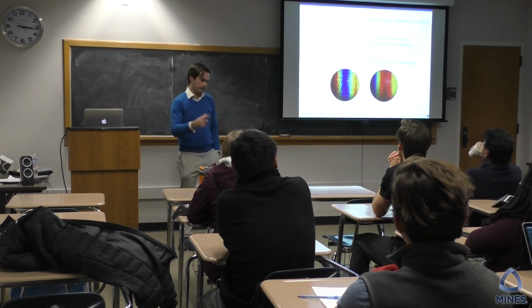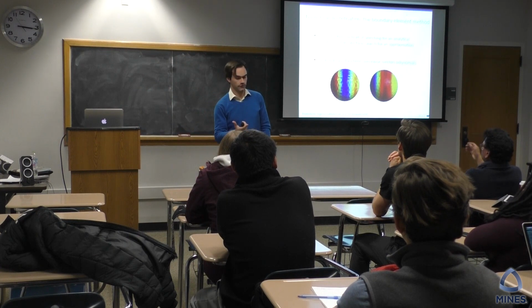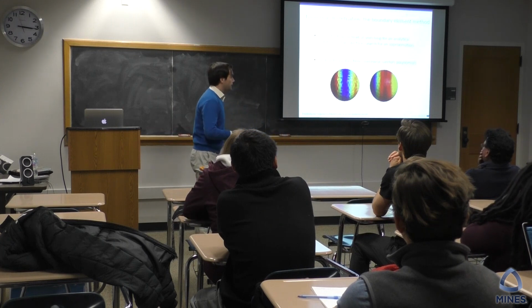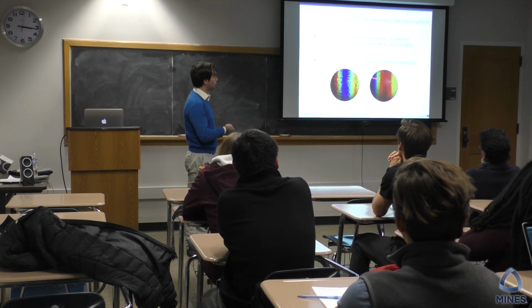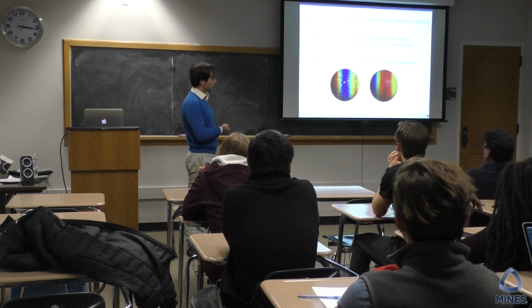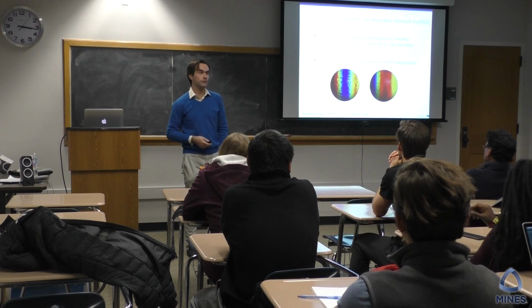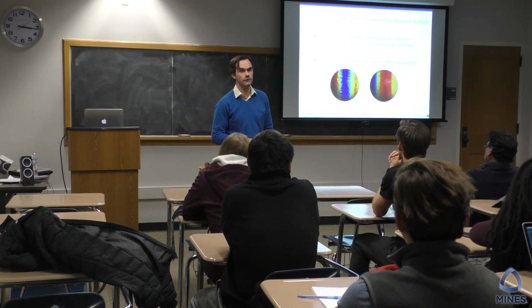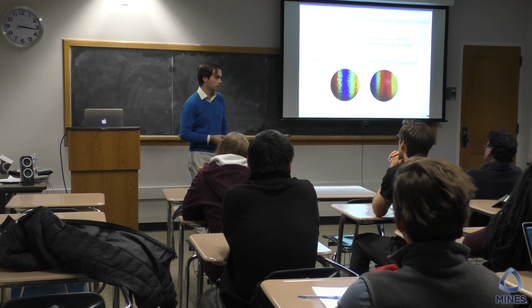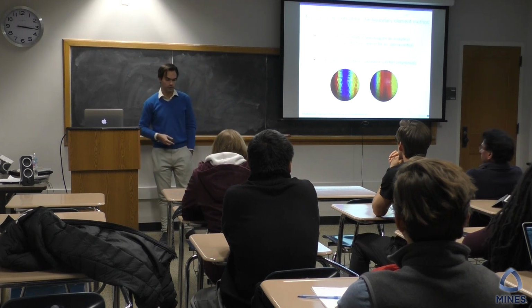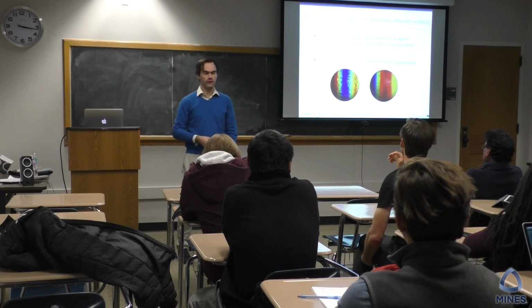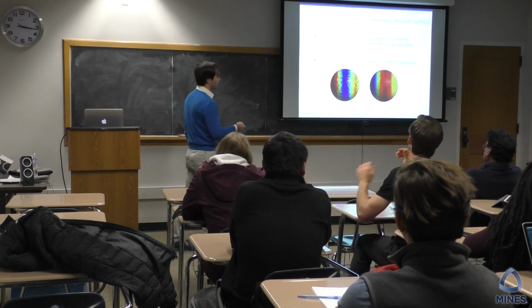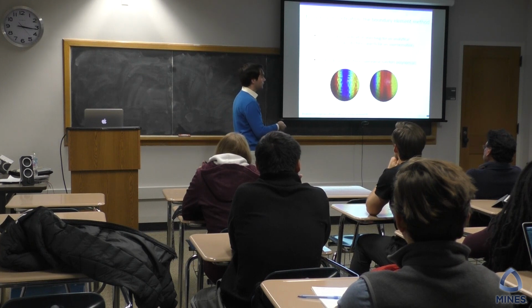So at the surface we have our integral equations, so we need to discretize at the surface. Here I have 2 examples of a sphere. You see we use triangular elements on the surface, so we mesh the surfaces with triangles. On the triangles, very similar to finite element methods, we need to choose test and basis functions for our variational formulation. These are piecewise constant functions, and these are piecewise linear functions.